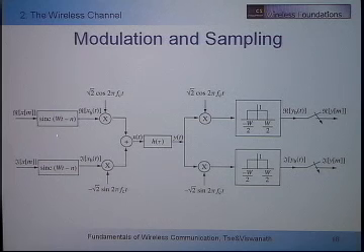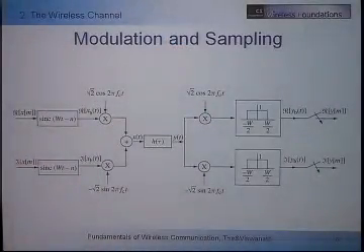Okay? This waveform can be many different types of waveforms, but for simplicity, we focus on the simplest waveform, the sinc waveform. So we have a bandwidth of interest W, okay? And with these waveforms, we're essentially operating at the Nyquist rate here. The waveform is consistent with the bandwidth W. At the receiver, I basically filter it to the bandwidth of W, and then I sample at the receiver. Sampling means projecting it onto the sinc function. So that operation matches the transmitter.